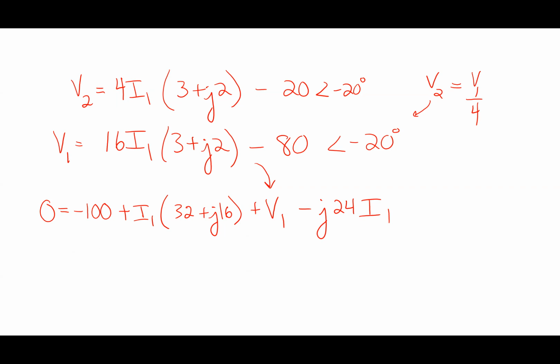And then we're going to start basically saying, okay, well, let's put this guy into a quote unquote power system where we have power in an AC sense. So power in DC was easy. All you had was resistors. Now we've got capacitors and inductors. Resistors eat power. They eat energy, right? They basically consume energy. Inductors and capacitors store it. That's different. So the whole power thing becomes completely different when I talk about AC stuff. All right, so we'll talk about that more beginning on Wednesday. Okay. All right. Any questions?